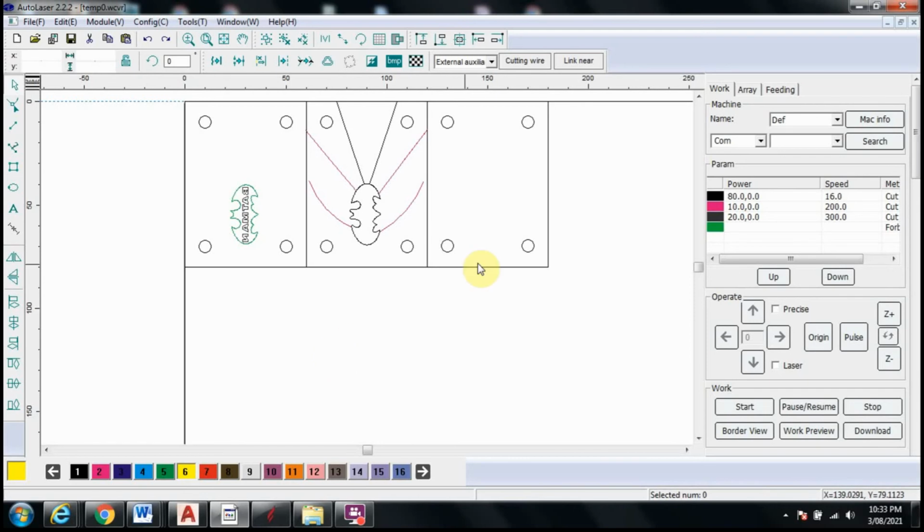The first thing I'm going to do now is to actually start looking at my layers. Over here you'll see the layers that are currently in my drawing, and each layer has its own cut setting assigned to it. This one down the bottom here says forbidden, and that's sometimes useful for us to do, but I'm not going to get into that now. Now those colours coincide with these down here, so if I did want to create a new layer I could click on that and draw something in, but that's not what I really need to do. We can leave those set up with the different cut settings like I do on my laptop, but often, and especially if you're going to be using the school laptop, they won't be preset to specific materials or thicknesses or anything like that.